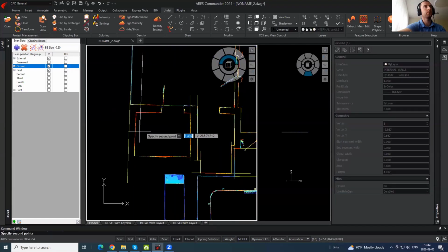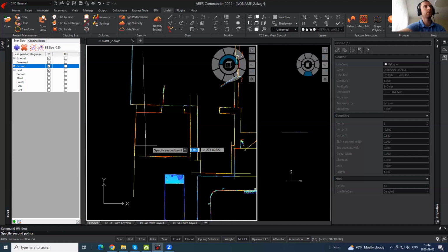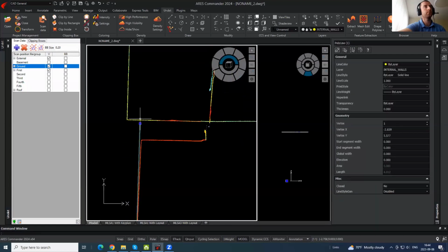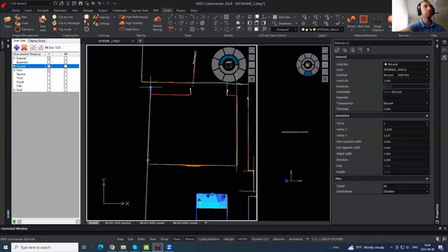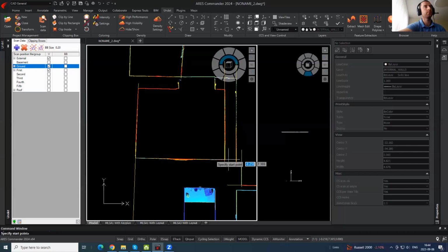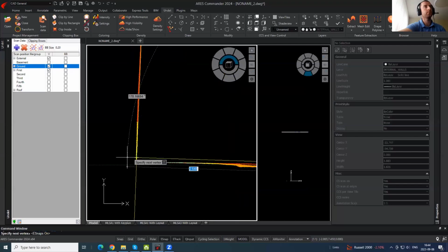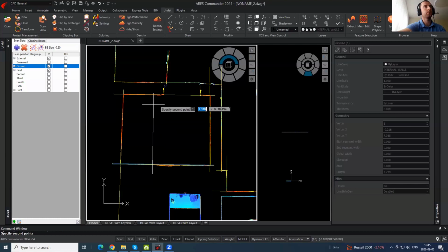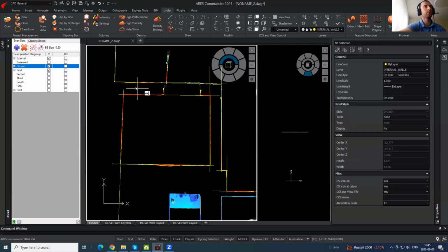Some of them are copied, some drawn by the polyline command. Out of accuracy, let's try to change the corner. Also, we can switch perpendicular snap, see if it works. If not, then okay, let's use our corner and try to make them parallel to each other.